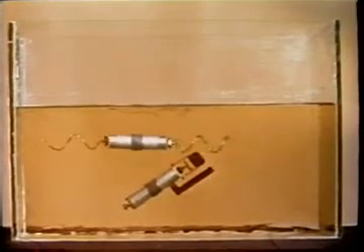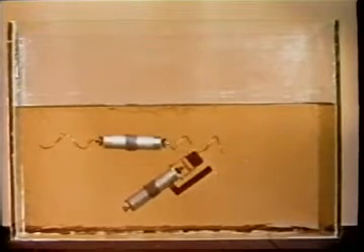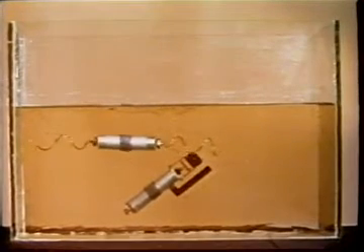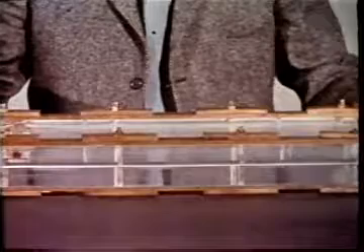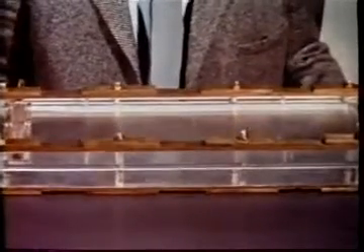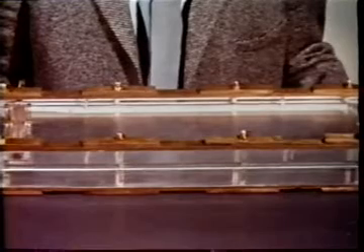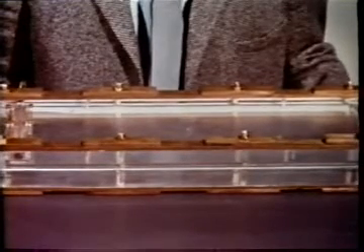The last example I will show of low Reynolds number flow is that between two parallel plates separated by a very small gap. This arrangement, known as the Hele-Shaw cell, has a special interest because, paradoxically, it offers a means for making visible the streamlines in certain cases of ideal flow of a non-viscous fluid. The gap between these two thick plastic plates is formed by this gasket.